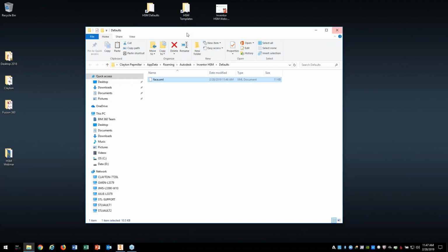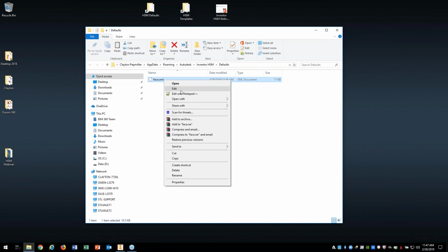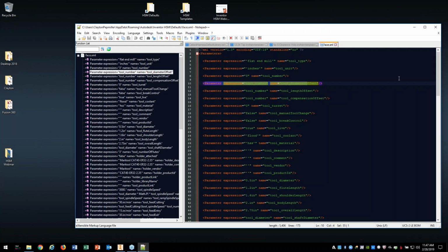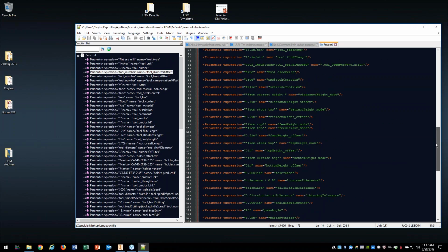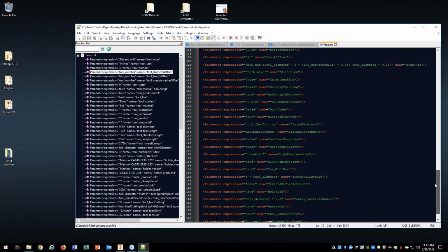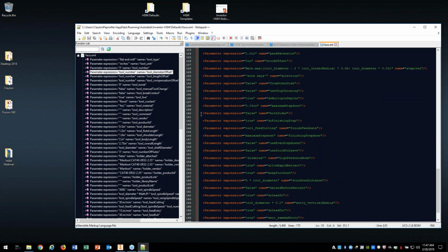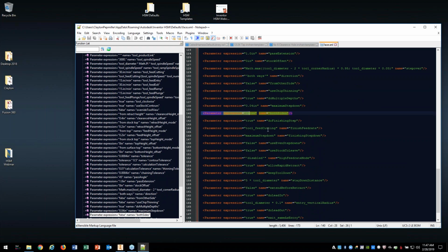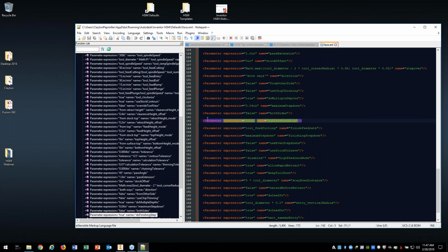Now, to prove the point here, I'm going to go behind the scenes again. I do a quick edit on this face XML. You'll notice there are a lot of lines of code here. There's one line of code I'm going to show you in particular. I thought it was line 142. There we go. Line 142. There's an expression statement here that says, do finishing step, true. That's that checkbox that says, turn on the finishing step.